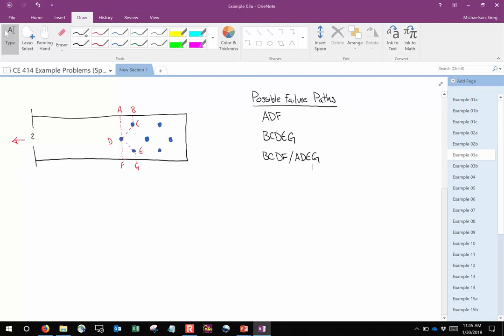All right. So let's just sort of summarize our math so far. We have a gross area of, what was it, 12 square inches? We have a stagger factor of 0.161. Well, we know the thickness of the plate, and what's the thickness of the plate? 1 inch. And we know the hole diameter is 0.875.